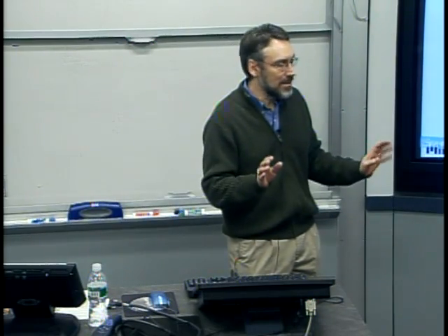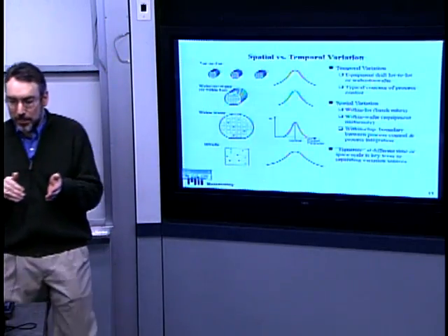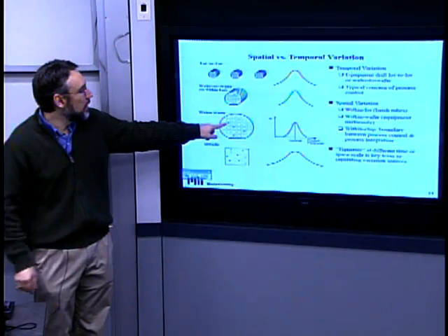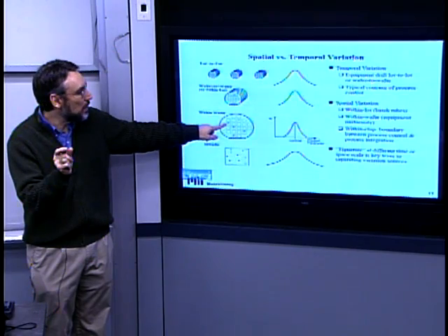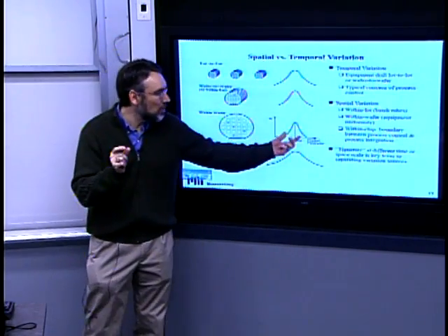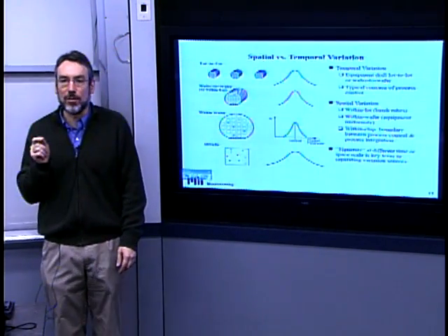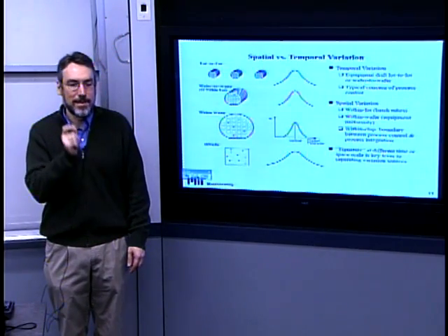And so much more broadly than defects, we're much more concerned with continuous parameter control of geometry as well as some of these other properties that we saw in the sequence. So for example, that critical dimension control might be the channel length of transistors on my device, and inherently you're going to have some statistical distribution on channel length.